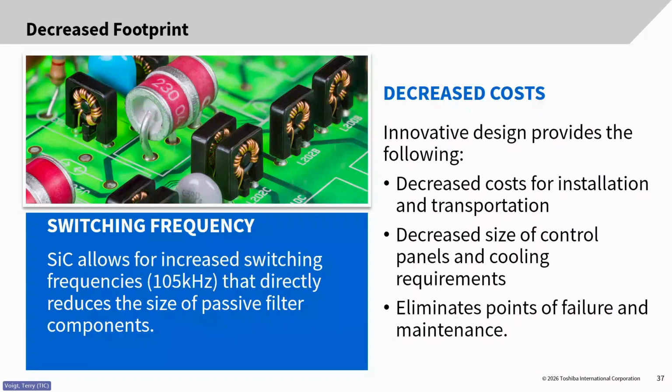I mentioned earlier that the effective frequency is 210. The reason why we double the effective is because it has a stepped waveform. The waveform on the output actually has multi-levels, so it's a multi-level output. So the effective frequency is double the actual carrier frequency.